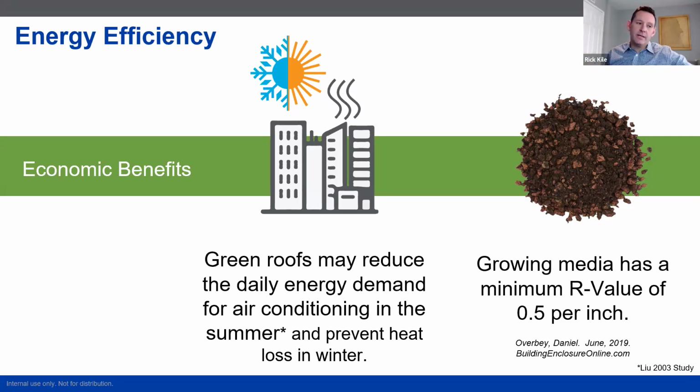Yeah, just from a roofing manufacturer's perspective, I don't think roofing manufacturers look at it as we're putting a vegetated roof over our membrane, so we're going to extend the life or the guarantee period or the term. That really boils down to how that is being specified as a membrane specifier, and what term are you looking for? I think most common in the industry, we're looking at 20, 25 years for a membrane guaranteed.